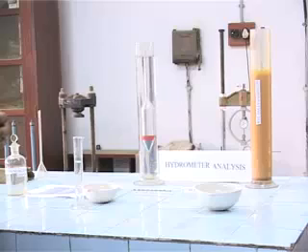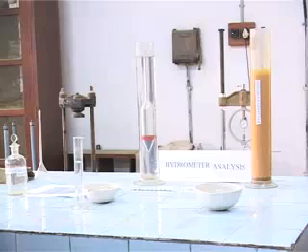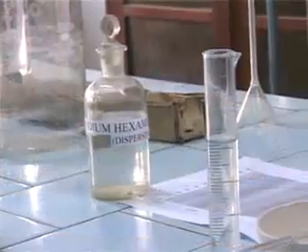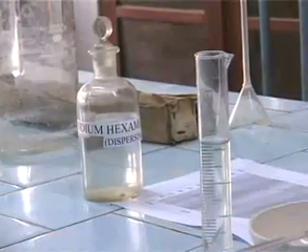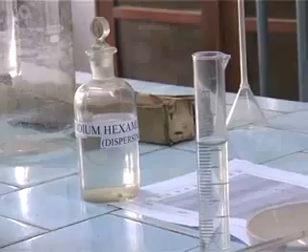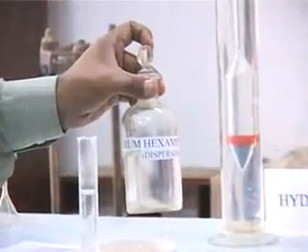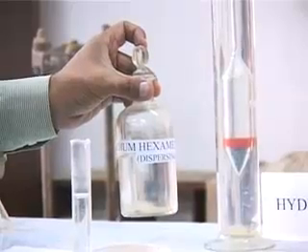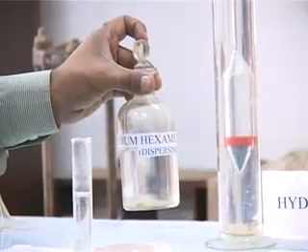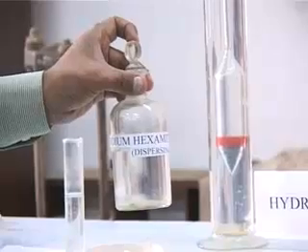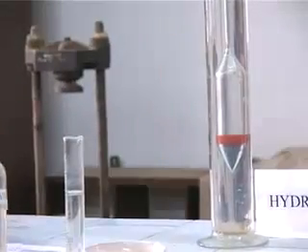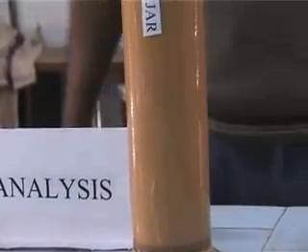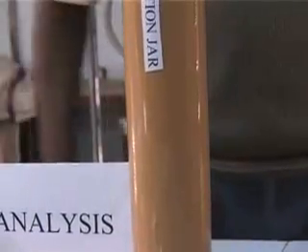We also mix it up with about 20 ml of sodium hexametaphosphate solution, which acts as a dispersing agent so that individual soil particles do not cling together forming clasts, so that the settlement rate is not wrongly measured, because the clasts are going to settle at a faster rate than the individual fine-grained soil particles.